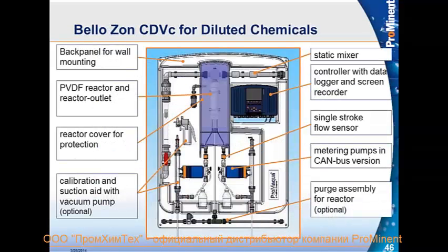This is what the unit actually consists of. 2 metering pumps, which give you the exact amounts of the precursor chemicals fed into a reactor. Now, this reactor is only an aqueous phase. There is no gas in this reactor. It is mixed with a water solution, which creates an aqueous solution of chlorine dioxide at 2% or 20,000 ppm. Under pressure, that solution then goes through a back pressure valve here. It's mixed in with your bypass water.